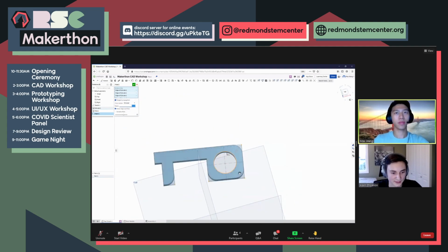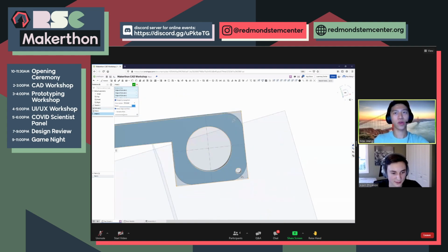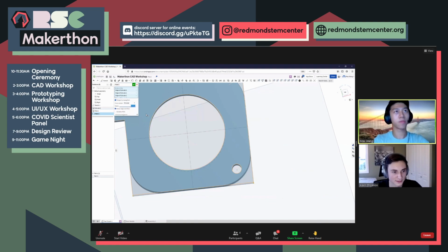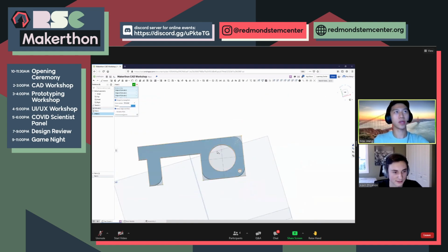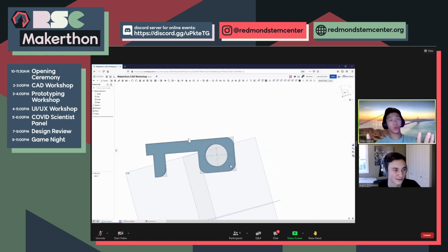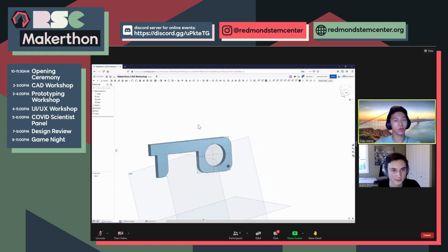I like that. It's more of a curve, or maybe 0.35. There we go. Give us a little more thickness. Okay, perfect. Now that's the fillet tool. So it just smooths edges. It's nice if you want smooth edges, or if you just want to not have a sharp edge on something, just for safety concerns. So that's what the fillet tool is generally used for.